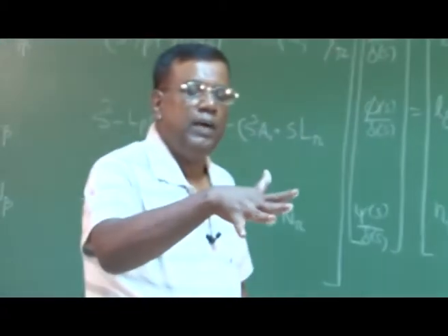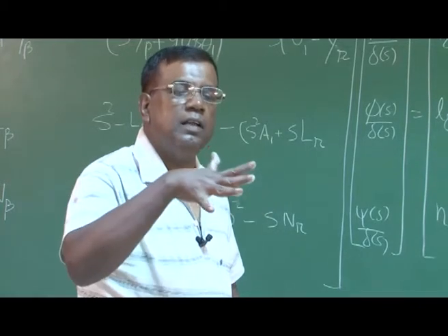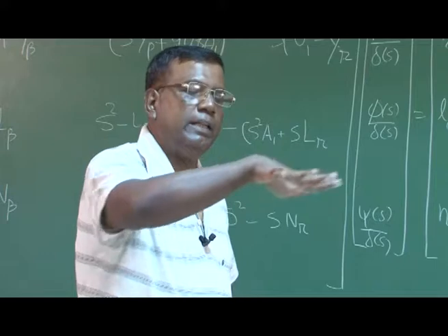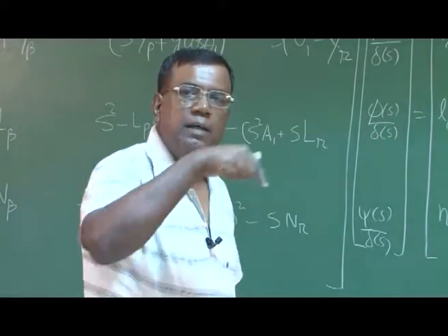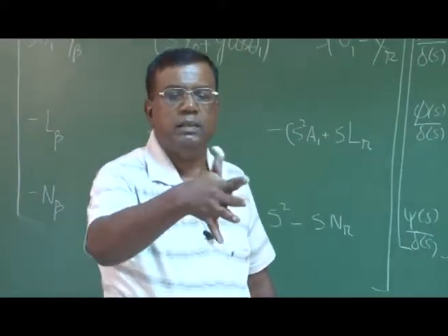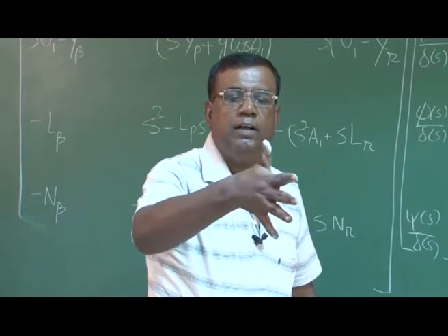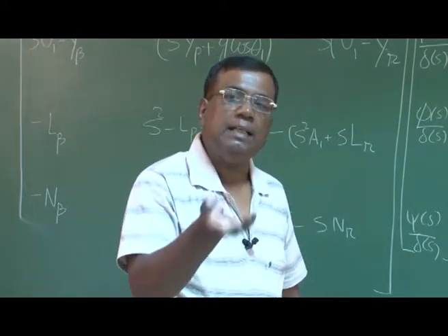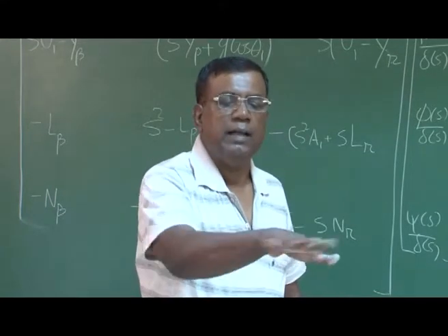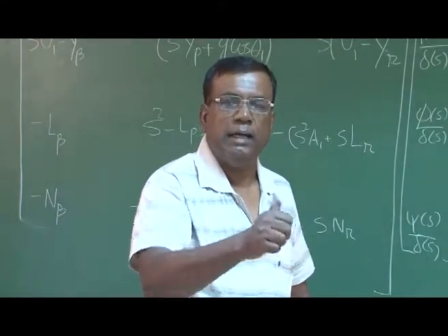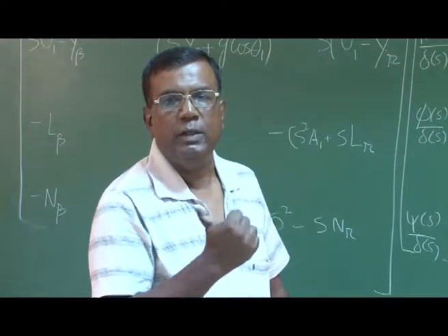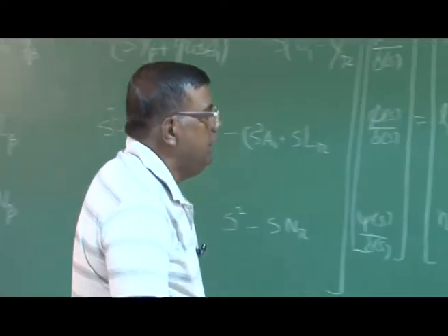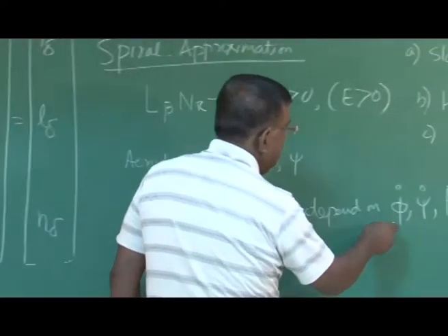If it is phi, the aerodynamic force has nothing to do with it because of the relative airspeed. Whether it's going like this, or going like this, the relative air is the same. However, phi dot is this. As there is a phi dot, there is a relative airspeed vertically up. That gives the aerodynamic forces. Similarly, with psi dot, there is a rate, so that will also give an induced beta, which will give you aerodynamic forces. That is why it is important to first identify this.